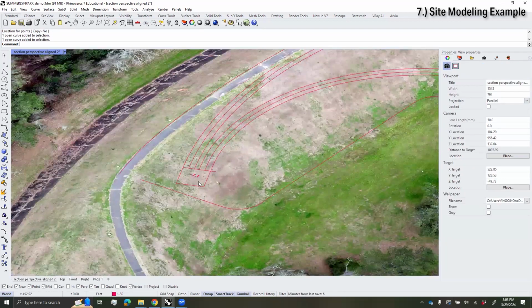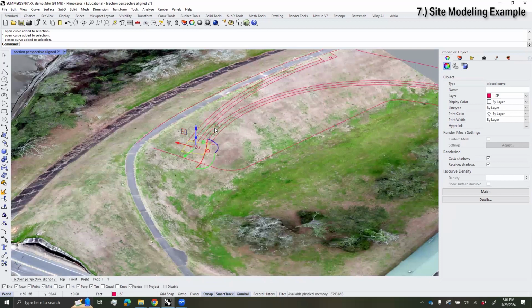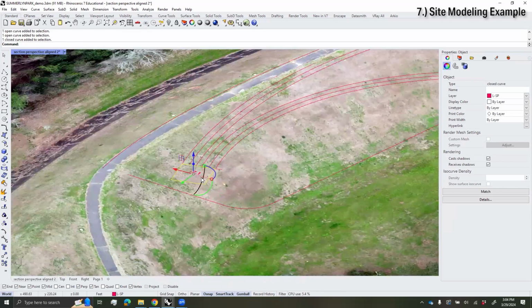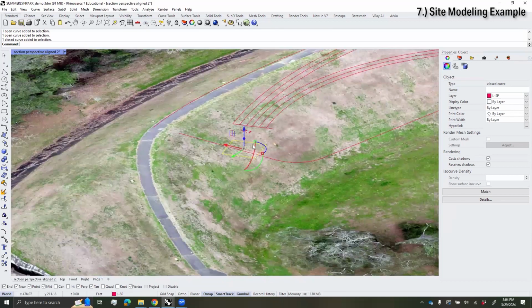You see that I have the line work sort of projected to the top of, in this case, this berm here. First thing we'll do is take, let's say, for instance, this landing here, and I calculated the 5% slope for this length here to be negative 7.1 feet. So I'm just going to move that down negative 7.1. So that's down at the elevation that needs to be.